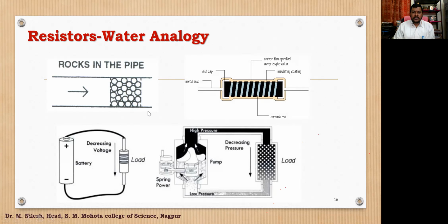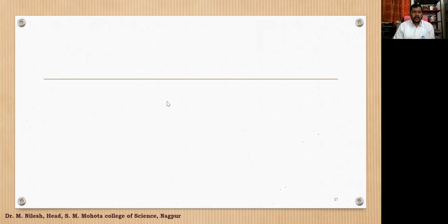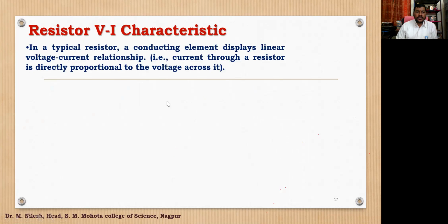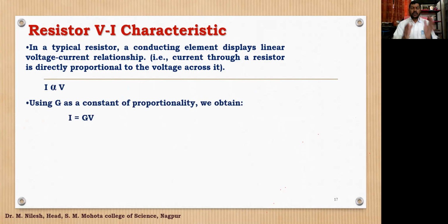Then this is the resistance that I have shown you, and yeah, resistance VI characteristics. Now, in every one of the practicals that we are going to study in this session, we will have VI characteristics, which means voltage and current characteristics. So voltage is to be taken on the x-axis, and the current is to be taken on the y-axis, and accordingly we draw the graph, right? So we call it a VI characteristic.